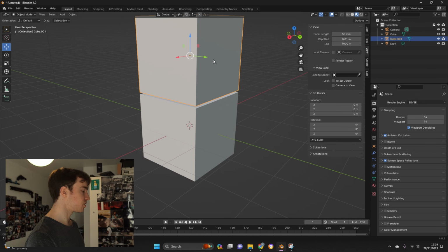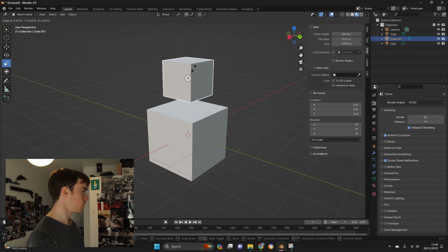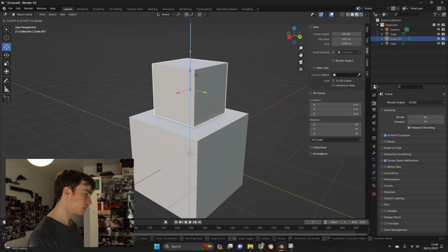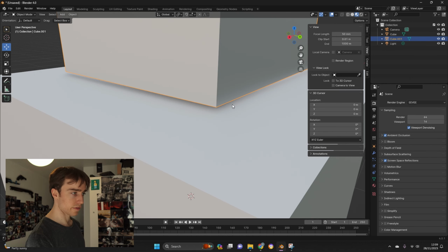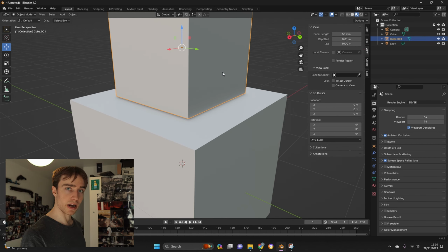But anyway, let's just show you what ambient occlusion does with this cube. So what we'll do is we'll shrink it down by using the scale tool, and let's just bring it close to the other cube, and what you can see is this slight shadow effect, and that is what ambient occlusion does. It gives us a clearer way to see that effect of objects coming closer together. Select that just so you can see that effect. Looks more realistic. But yeah, X, D to get rid of it.